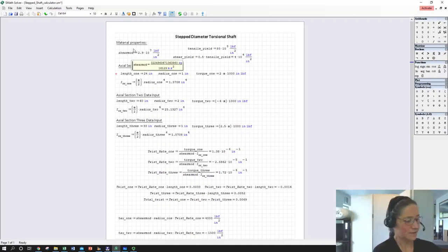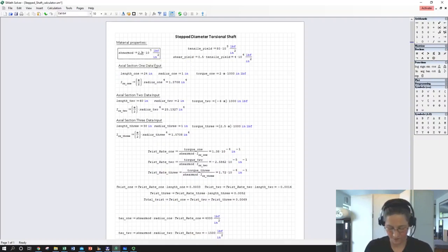I am looking at my old book of material properties, and so I took a look at a ubiquitous stainless steel and pulled out a value for shear modulus, and I'm used to using the gigapascal numbers, and I just realized I actually added the tensile modulus, so I'm going to change that on the fly here. I'm finding a shear modulus for stainless of 11 times 10 to the 6 psi. So I have this in 10 to the 7th, so I would do 1.1 times 10 to the 7th. So now I have the appropriate shear modulus.